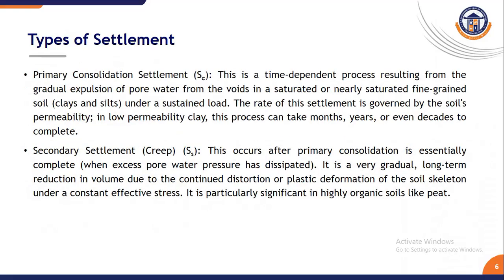After that, primary consolidation settlement. This occurs due to expulsion of pore water from saturated fine-grained soil under sustained loading. This process is time dependent and controlled by soil permeability. A simple example is in clayey soil, where a building may continue settling for several years as water slowly drains out of the soil pores.